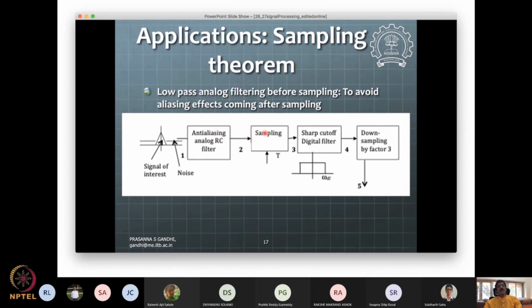And then when you sample it, the samples will be represented in some way. Then you can see how the signal looks after sampling, and with what frequency I should sample, so that this tapering off part does not get mixed with the signal itself. The signal of interest we need to preserve under the sampling.